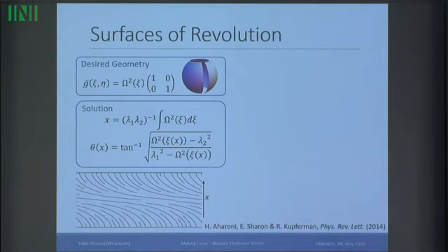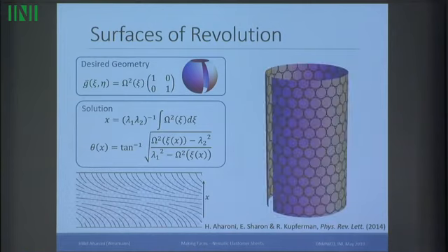So making a nematic elastomer sheet with this director field, upon actuation, will deform into the sphere. In order to see this, I drew tiny circles on my ribbon, and I put it here in the shape of the cylinder, right? This doesn't take any deformation. You can easily deform a flat piece of paper into a cylinder. But now imagine that this is inside some temperature bath, and once I raise the temperature, every circle here deforms into an ellipse.